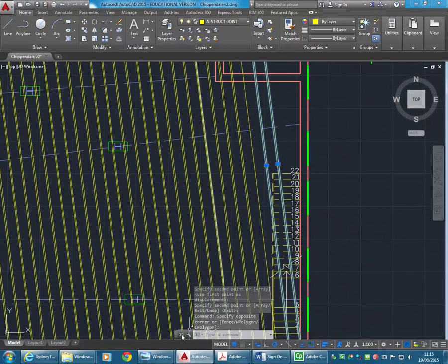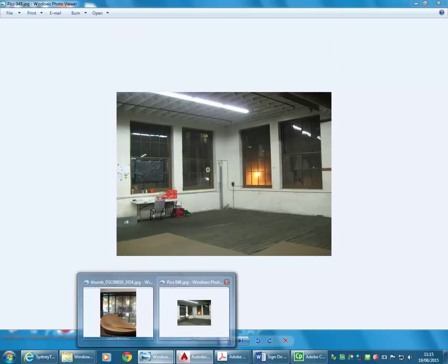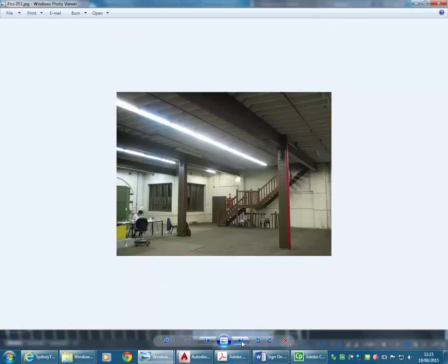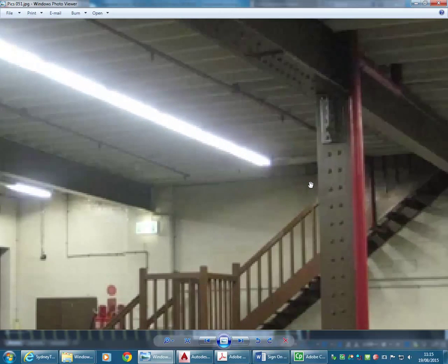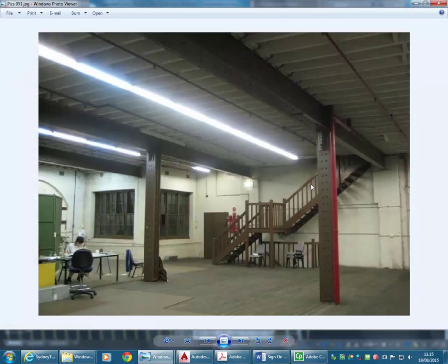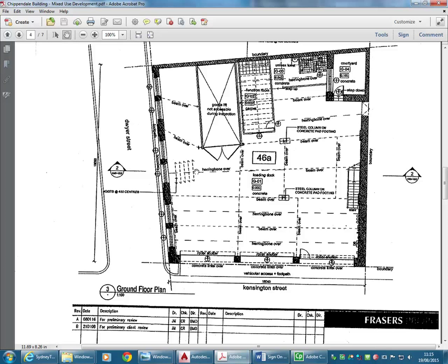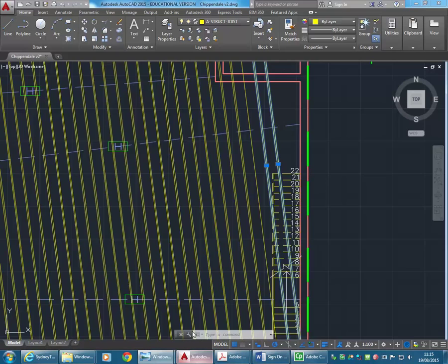So this is where it's a bit strange, and we might want to check. So let's have a look against the stairs. Yeah, look, I don't know that they got it right in the drawings. So having done all of that, I've now realised. Yeah, I think it is, which is good because that's much easier. Okay, so let's just say this drawing is wrong. They got the beams right, but they were wrong about the joists. So that's good to know. Okay, so at least you know how to do it if you need to do a joist at an angle like that.